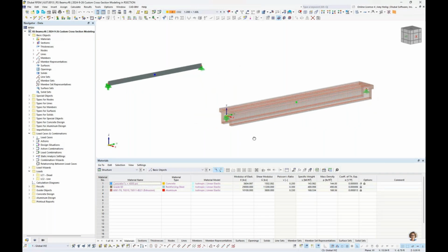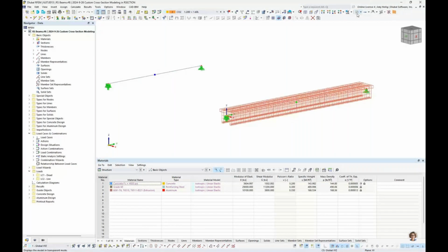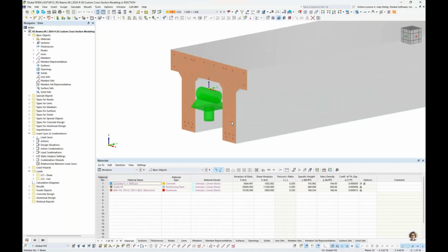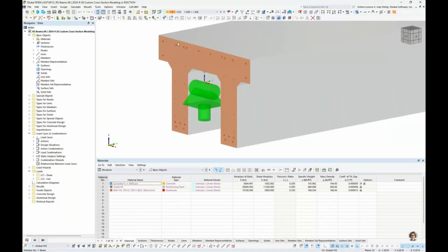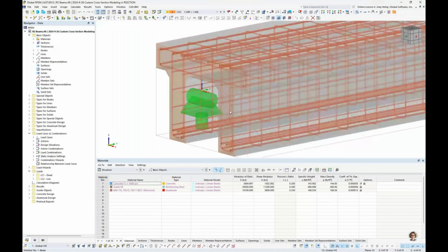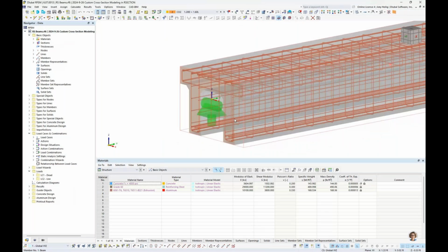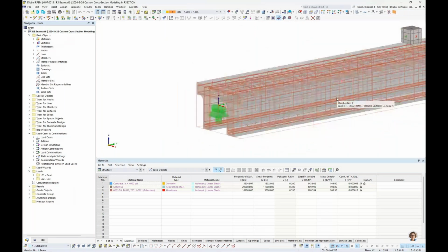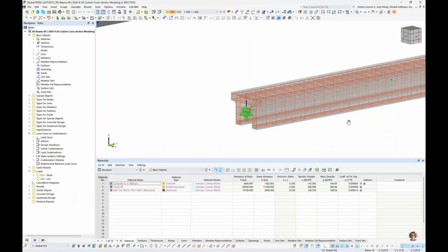So what you'll notice is I did create a couple beam members here utilizing our R section files. And we'll begin with, if I render this to a solid view, you can see our custom reinforced concrete section that we just defined. So what's nice is you see the rendered shape for this cross section. And if I turn this into a transparent view, we also see all of the reinforcement that we have applied to this cross section. So this member is 30 feet long.